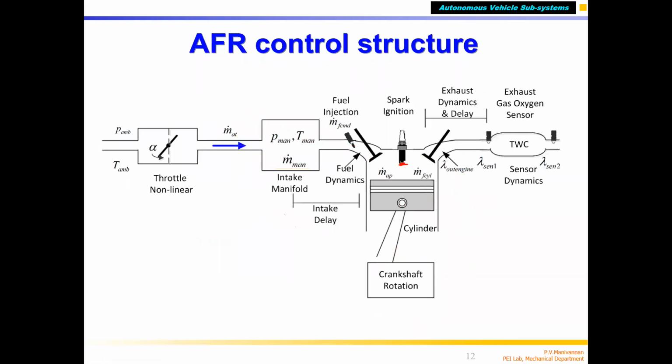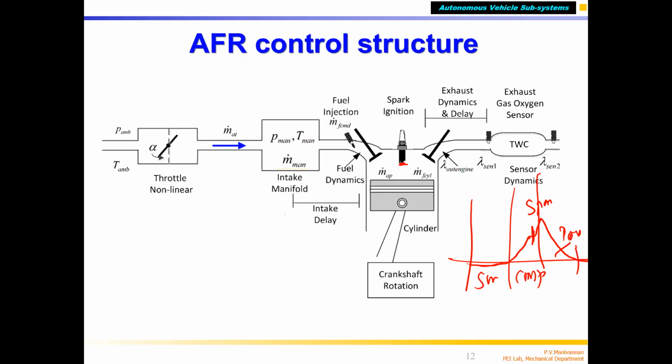As I told you, this is the suction stroke, then it comes down, it goes up. Here you are giving the spark. This is the compression, this is the suction, this is the power stroke, and this part is exhaust. So in the compression stroke, just near the end, you're giving a spark. Where? Here. So that means combustion starts here.